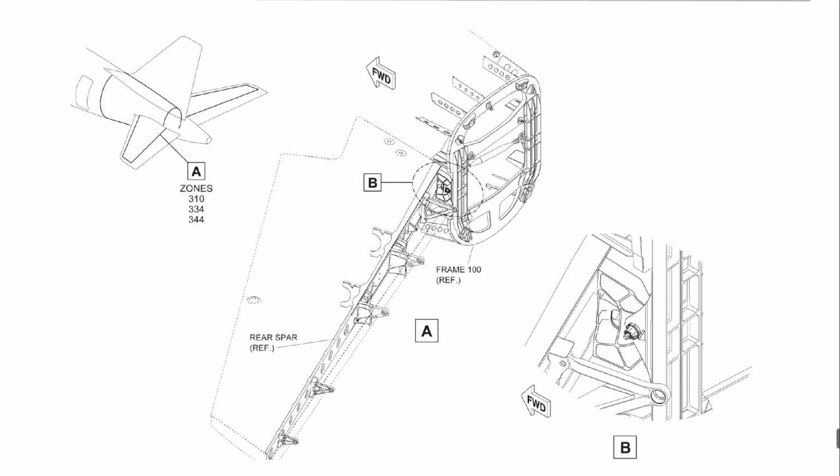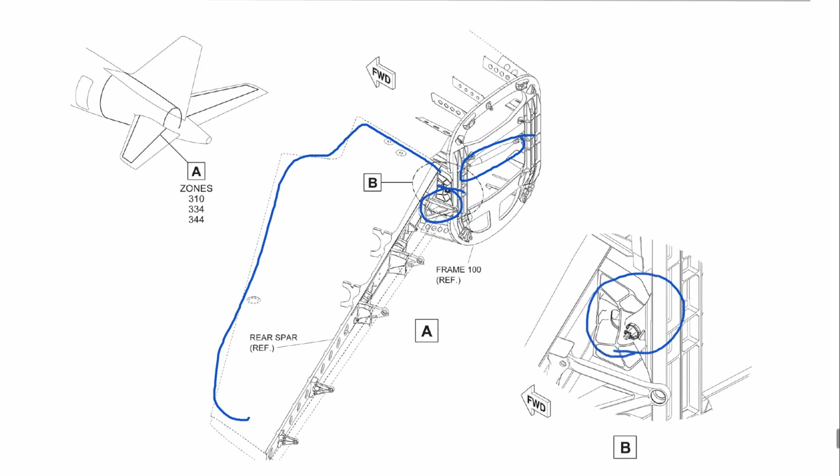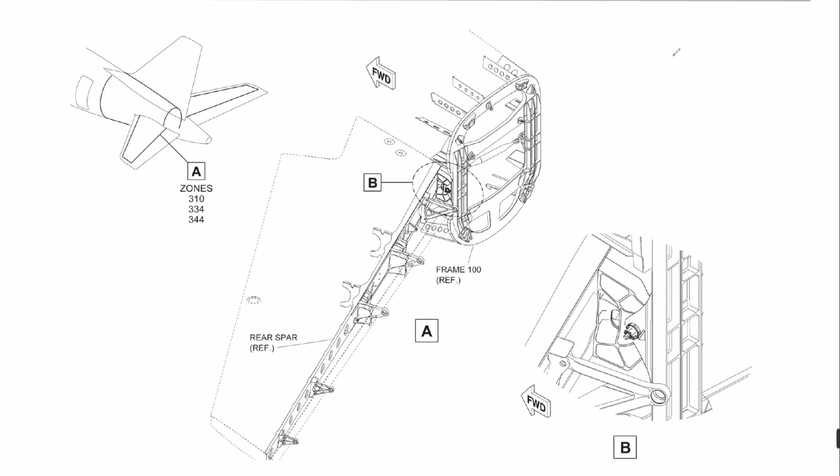Just a second. Have a look. So this is the horizontal stabilizer, and we have these attachments here. We have rods which are keeping together the structure. This is how it is attached with closer look here. Again, with bolts and nuts. And again, we have a really strong structure because there are a lot of high aerodynamic loads coming from the elevator and the horizontal stabilizer, like in general.